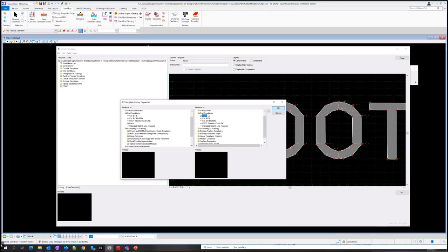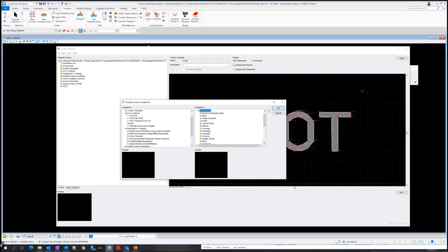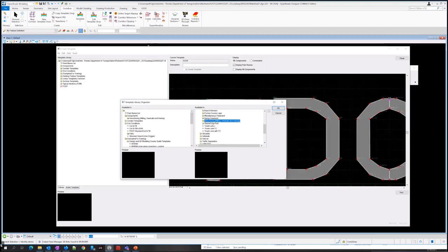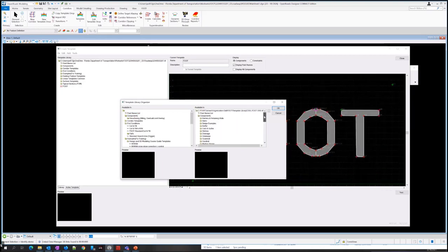And we need also, this is a table under step 8 that I'm going through, we need also the resurfacing components. So if we go under components, pavement, resurfacing. There's nothing in here right now, the blank one. So we'll just copy that one over, drop it in there. Now we've got something in there. And also we need the curb and gutter components. So I'm going to grab this folder and also drop it in the components folder. And we need the linear templates common.